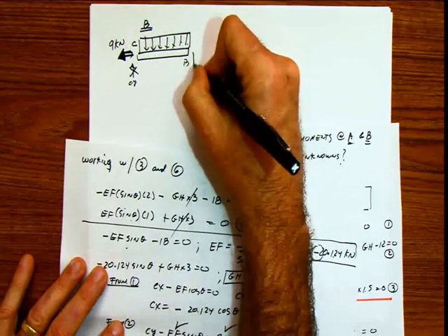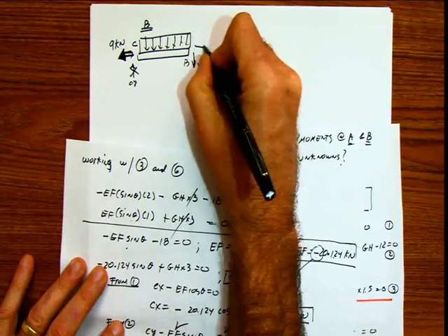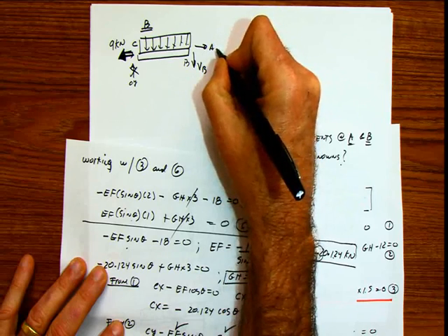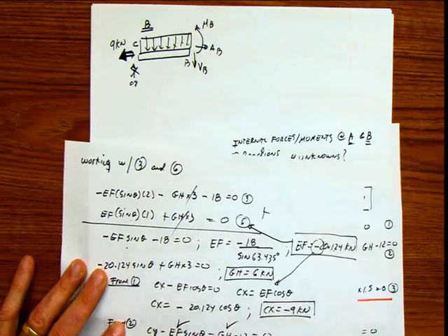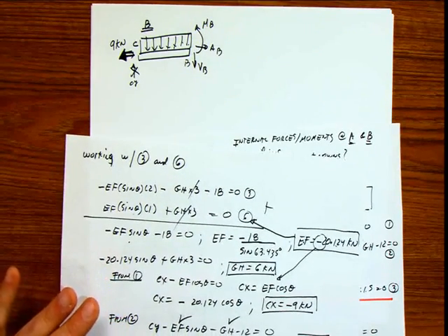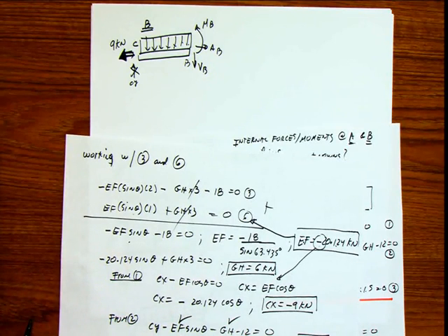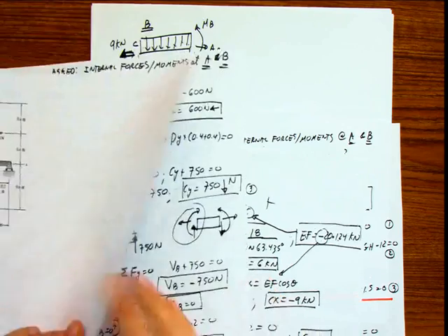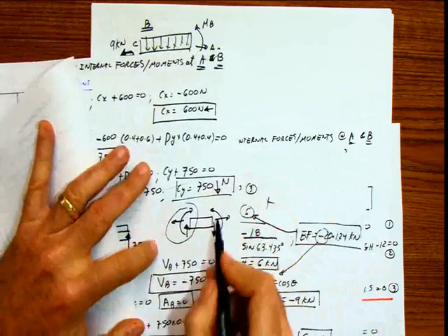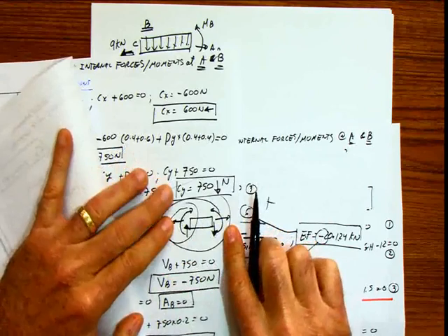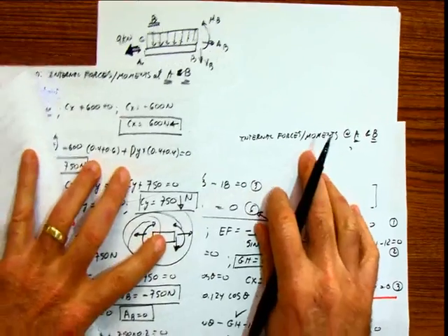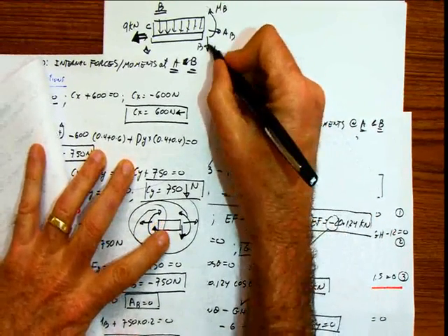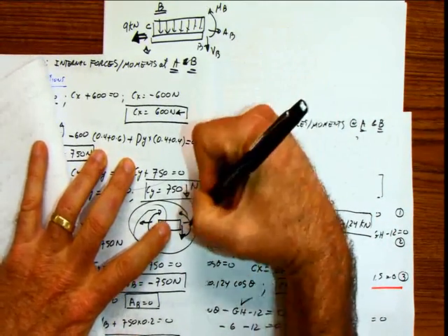And of course here I'm going to have my shear at B, my axial at B, and my moment at B. Guys, it's super important. Once again, I'm going to use the drawing that I did from the other problem. Don't try to match any number, because I'm not looking for the numbers, I'm looking for this. Look at that. This is the positive direction. You use this side, which is the one that we're using. The positive convention for shear, axial, and moment is that.